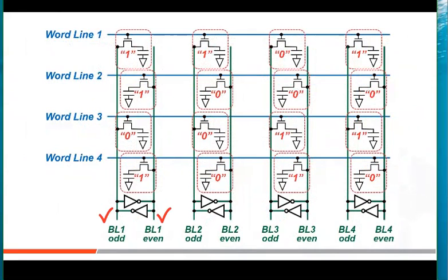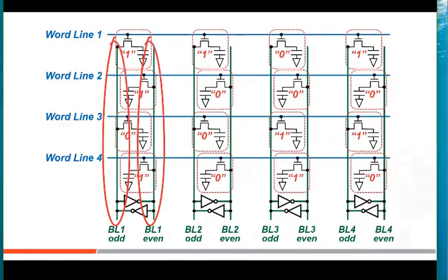Notice there are 2 bit lines for every memory column. We will call these even and odd. These are connected to every other memory cell in the column. Each pair of even and odd bit lines must be perfectly matched in layout, load and number of connections to do a refresh or read step.